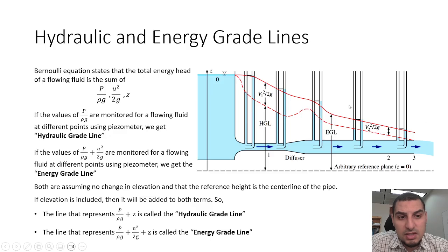What we see here is what really happens in reality, because while the fluid is flowing, there are friction losses and there is energy that's lost by the fluid, and this is why we assume an inviscid flow. Inviscid flow means that there is no loss, but here, since it's a viscid flow, there are losses. This is what we should see in reality. And this is, by the way, what we are going to discuss in the coming videos about the modification of Bernoulli equation to make it suitable for other cases.